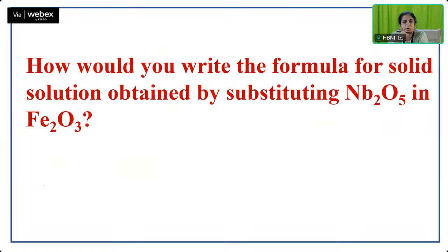Repeating it again for you, whether a solid solution will form and what would be the mechanism. When I say mechanism, I mean whether it would form by making vacancies, which we call anion deficient or cation deficient, or by putting in extra interstitials, which we call cation excess or anion excess, that can be determined only experimentally.